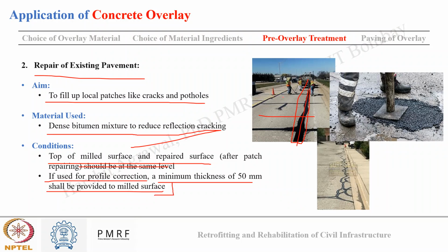So here you can see in this image, longitudinal and transverse cracking are filled using bituminous mixture. Here you can see again different small cracks are filled using bituminous mixture, and here you can see a pothole being filled and tamped properly for leveling it to the surface.